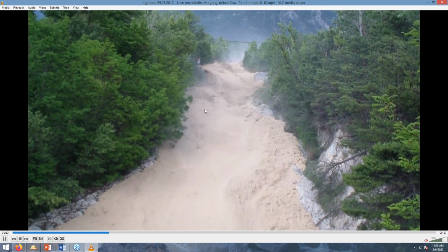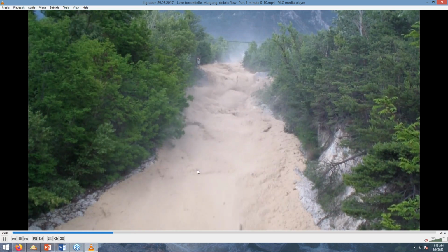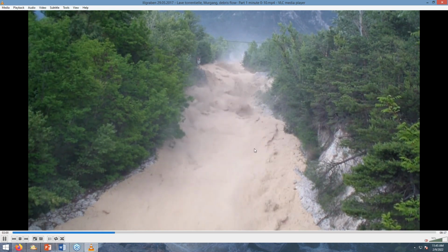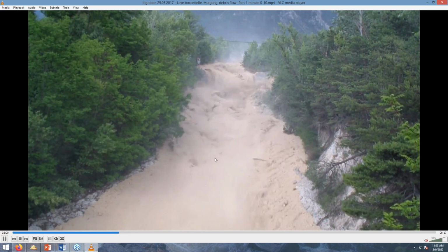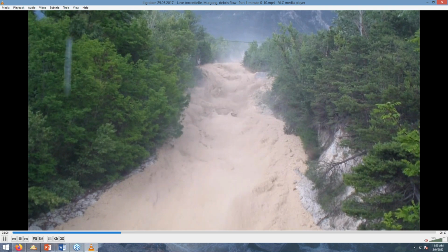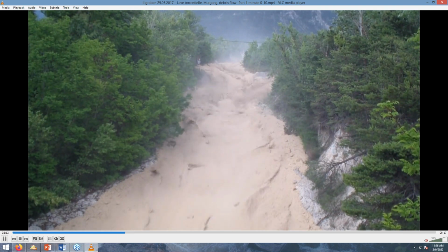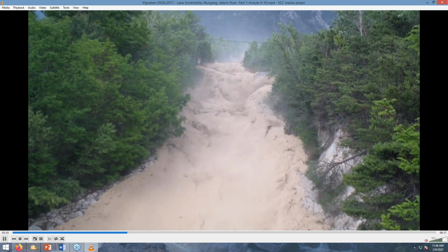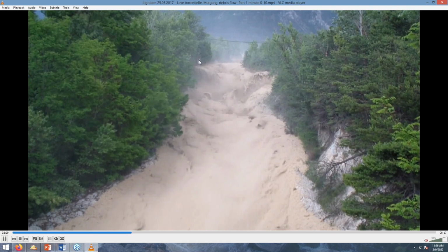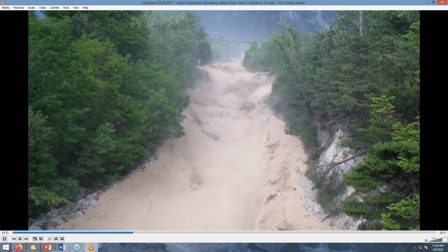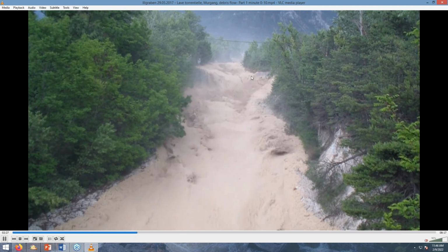And this has the shear zone effect that I was mentioning before here, where the flow is in the core of this. And you saw the more U-shaped type of channel associated with this event. I would suggest to you that this particular watershed must have this type of flood event occur very frequently because they've got this early warning system in place. And they also have, again, this Sabo dam type structure, which I'm not a big fan of.